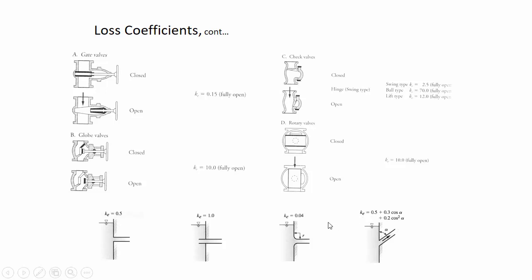But the angle that the pipe leaves can also contribute to the K value. And so here they're showing that if it was departing at an angle, not only are you having the water losing some energy as the flow is entering this pipe, but also it's changing directions. And so it's having to converge onto a small opening and then change directions as soon as it gets to that opening. So you'd have some additional losses having to do with the angle itself.